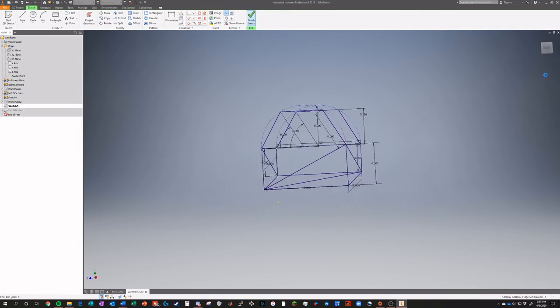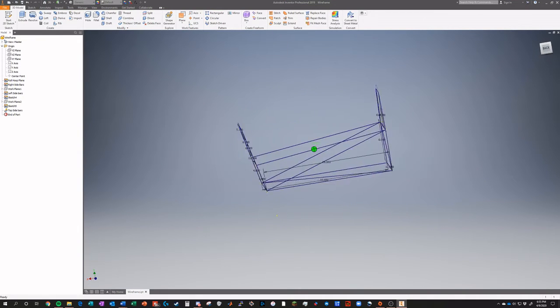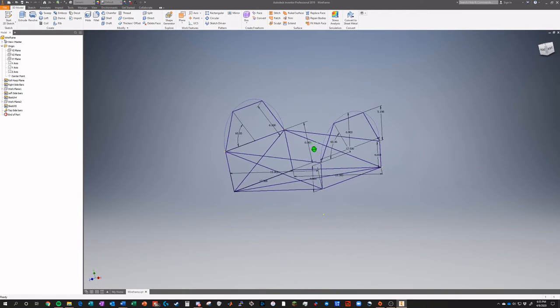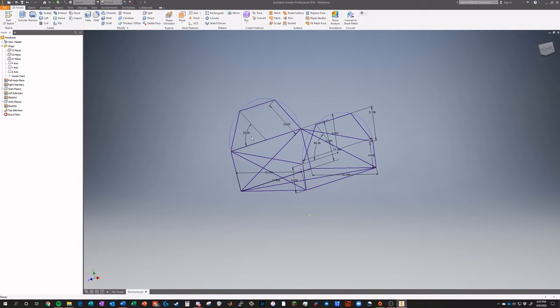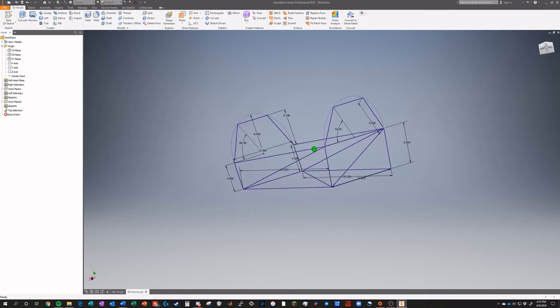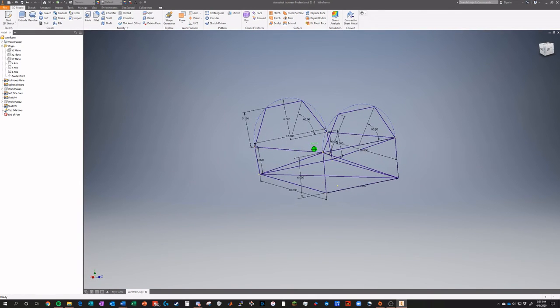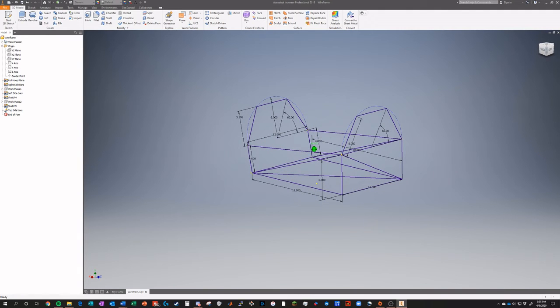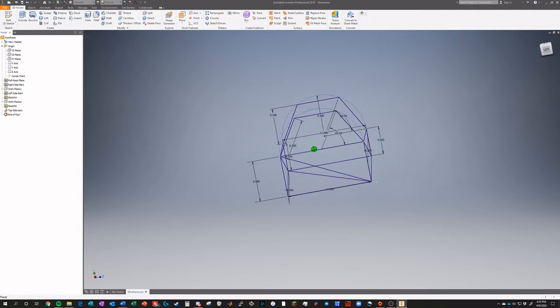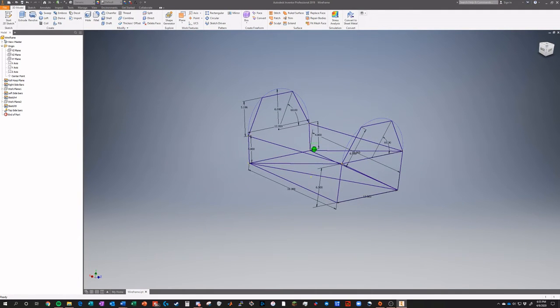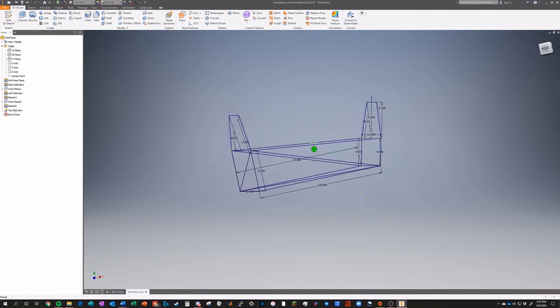Okay. So now we have a frame that we can simulate. Obviously, you could go ahead and do this in 4, or 5, or 6 to have even more accurate results. But in Formula SE, this particular application, the tube size for a lot of the bent tubes that we use, for example, the main roll hoop, is already specified in the rules, so that's actually not an area of design space that we're too interested in. However, it does affect the areas around it, so it is worth...